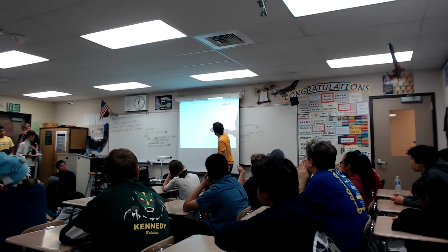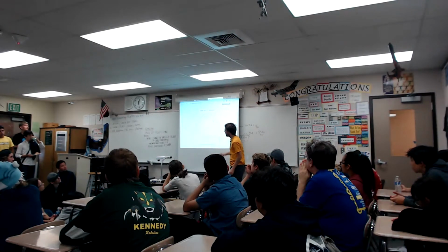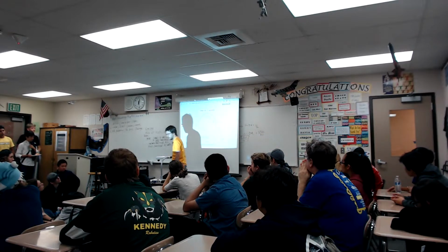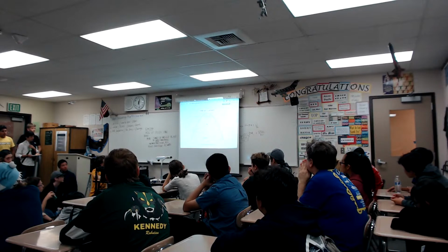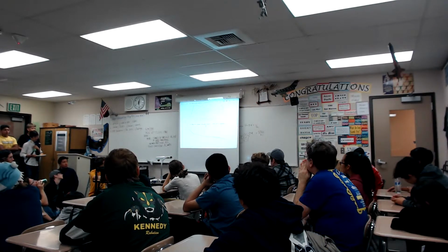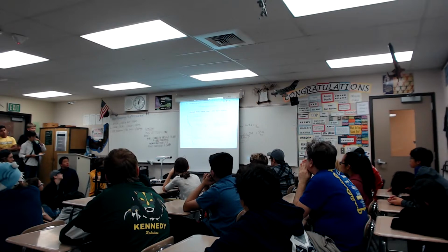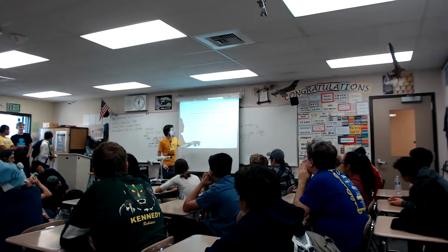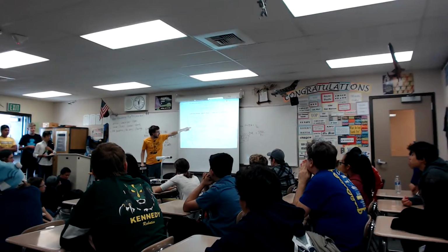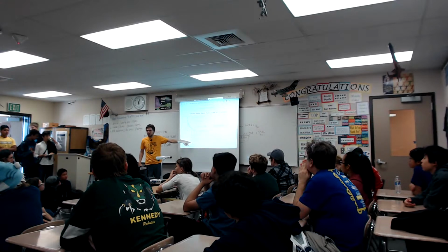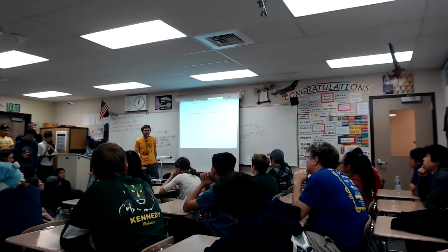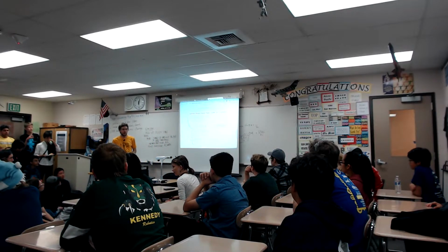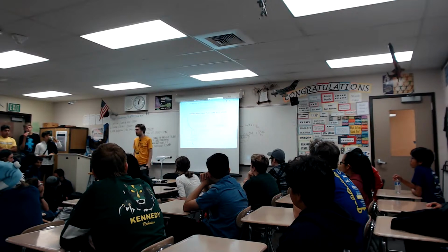And then here we can see torque. Torque and current are very closely related. So yeah, this is pretty cool. We're able to see our motor model. And this should be done experimentally, this graph here. And then this is one of my other favorite ones. This shows, given different motor voltages, you get out different torques. And then Aaron tells me that when these lines fall down, that's when smoke comes out of the motor and it stops working. So you can see how long you can apply different currents to your motor before it starts blowing up. This one's super helpful for helping size motors.